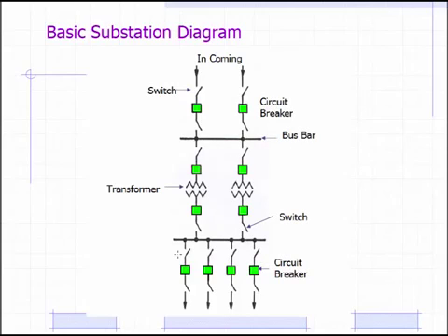You might have a bus that is made out of wire. We call that a string bus. You'll see buses that are made out of aluminum tubing. You'll see buses that are made out of angle iron or copper bars in switchgear. Those are all bus types you're going to see and deal with in this class. So there's kind of the bus. Bus just means it's a place that is a common electrical place.